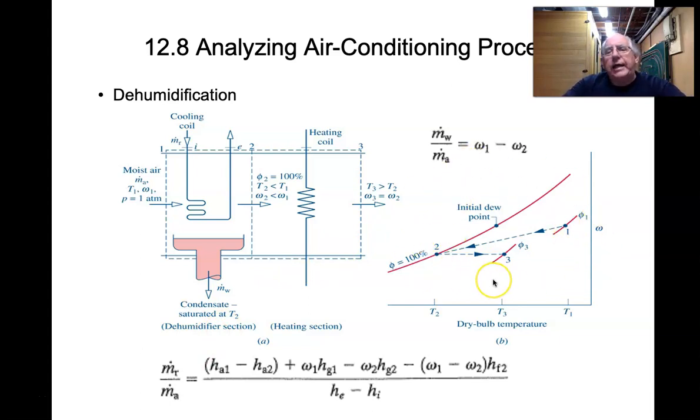And again, what it looks like on the psychrometric chart. Keep in mind, if this was a psychrometric chart with all the scales, there would be a line, an axis that would correspond to the enthalpy at a given condition. And so one could actually come up and grab this enthalpy value for this state, and it turns out that the enthalpy value for this state right here would actually be equal to this term in addition to this term.